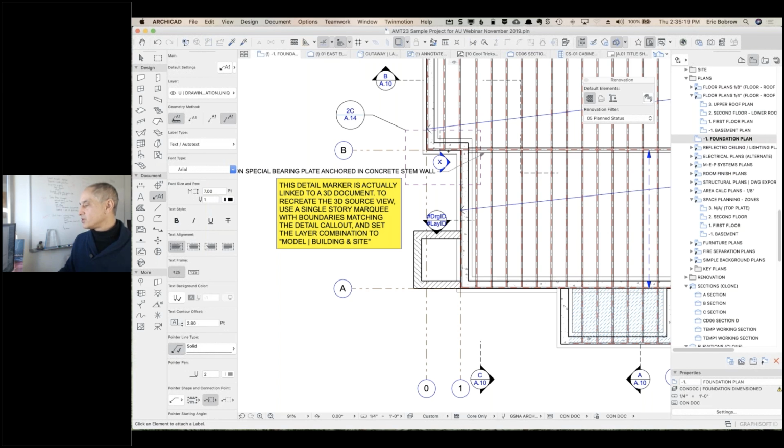Okay, so John Ryder says, CAD Image tools covering. So that's another thing for those vertical timber cladding. CAD Image has something called coverings. Again, you have to pay for it, but you can try it out for free. I think you can do it for a couple of weeks or 30 days. Basically you can use certain settings to put a surface on top of a wall, with these timbers. And you can also do things like having real tiles on top of the roof. And if the roof changes, you make the roof bigger or change its slope, the covering will adjust.